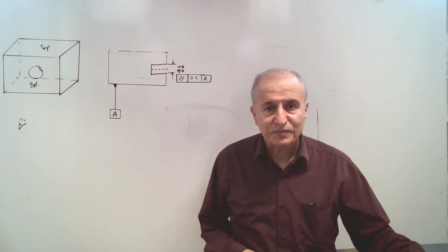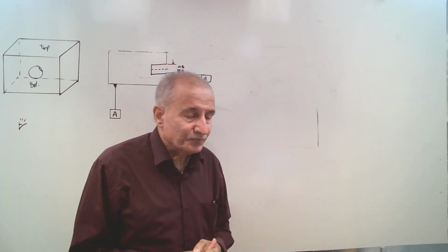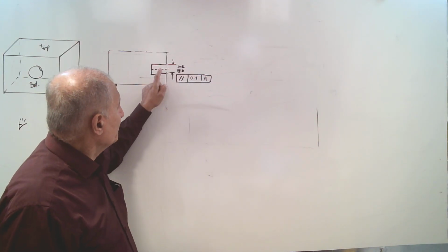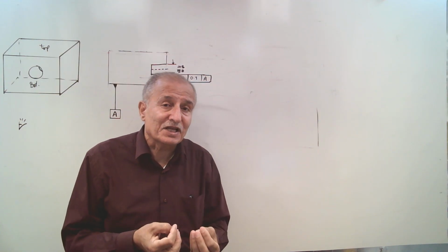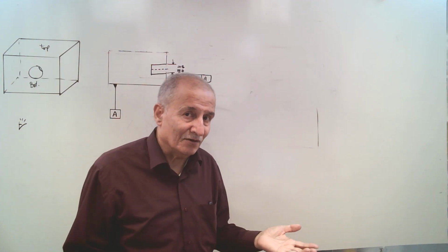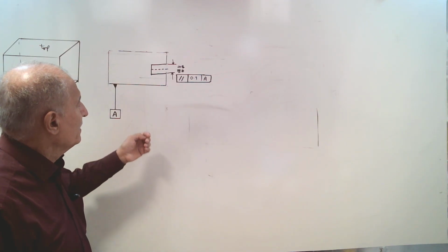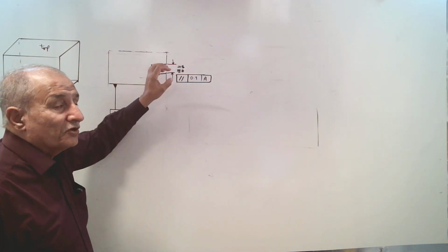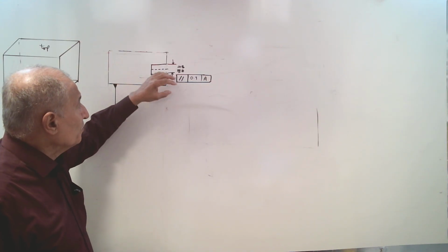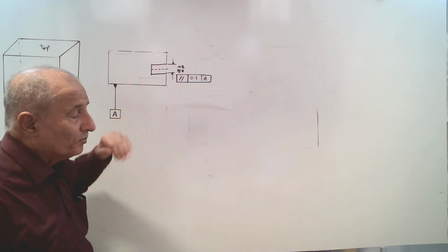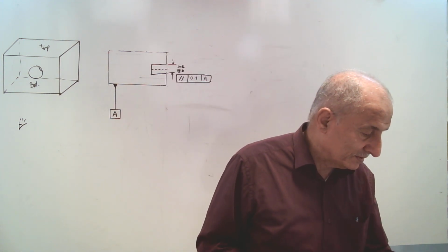What does it mean? It means that the center plane, which is the derived median plane, doesn't exist. It's only a set of points, derived median points that represent this surface. They must lie within a tolerance zone that is parallel to datum A, the bottom surface. That's datum A, the bottom surface.